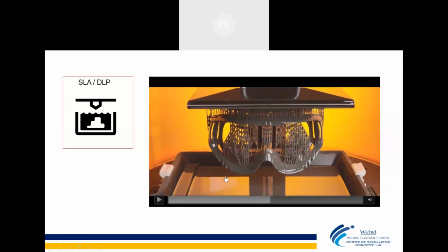So it has been deposited. You can see this liquid. The build tray goes inside the liquid. There is a laser at the bottom. The laser moves according to the dimensions of your product, and that gets solidified and printed. Okay, so this is one of the technologies known as SLA, another well-known and well-functioning technology.